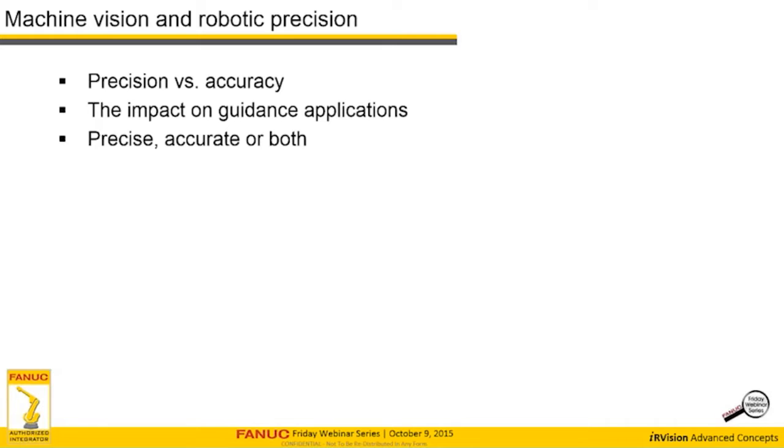The two key words as we think about an engineered system in robotics and machine vision are precision and accuracy. Precision is the concept of being able to be repeatable and reliable over a long run and over a large statistical sample set of your processing. Accuracy is quite more basically a term that relates to how accurate your system is able to reproduce a specific result. Precision can be independent of a specific result, whereas accuracy requires us to reproduce a specific result.